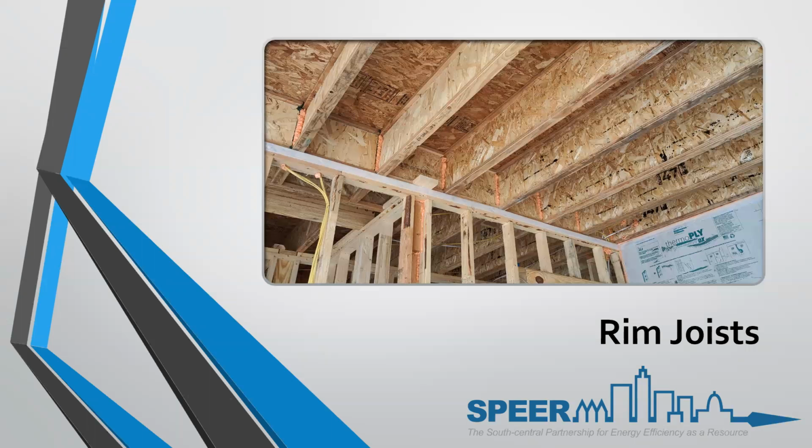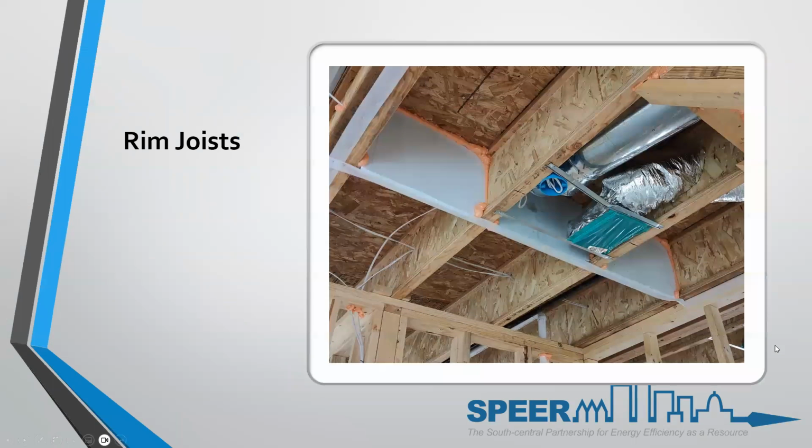Some people would leave that open and say, well, I'm insulating this floor over the garage, but therefore the other one doesn't have to be insulated because it's between conditioned spaces, which is true, but you must have an alignment of the air barrier, which is at the end of the insulation of the conditioned floor over the garage. So creating a band joist and air sealing, all of that is what's intended.